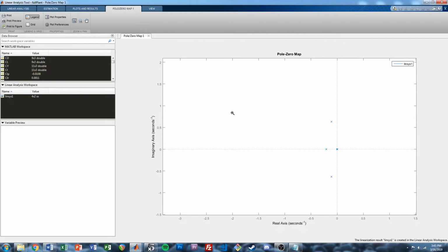So I think we did pretty good. You know, it doesn't match exactly because, I mentioned this in the last video too, there's some stuff in XFLR, some additional coupling that's being considered in developing the linear model that we're not modeling in Simulink. But I think this will be good enough for the controller design. Or we'll see, I guess. Who knows what's going to happen. But this should give you at least a good baseline. And then if you need to do some additional tuning based off of your test flights, you can do that as well. So the linear model looks good.